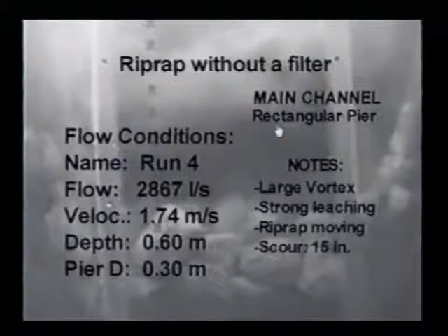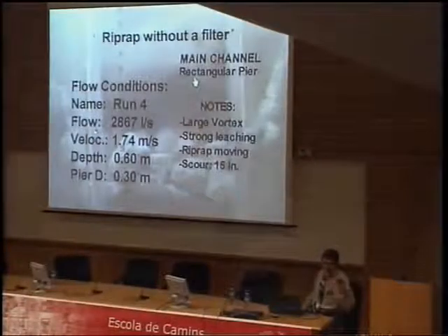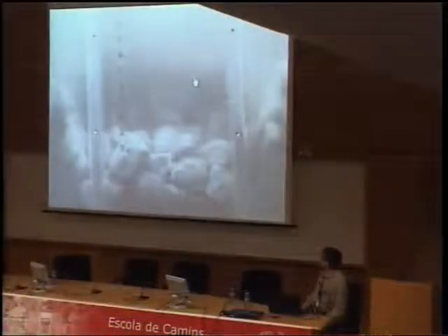This is our highest flow. And if you are an engineer who wishes to protect against scour, you have to protect against these kind of flow and sediment transport events. Again, you are looking upstream from the inside of the pier. Now you see an example with riprap, stones around the pier, and a geotextile underneath to help prevent the winnowing of sediment from the bottom.